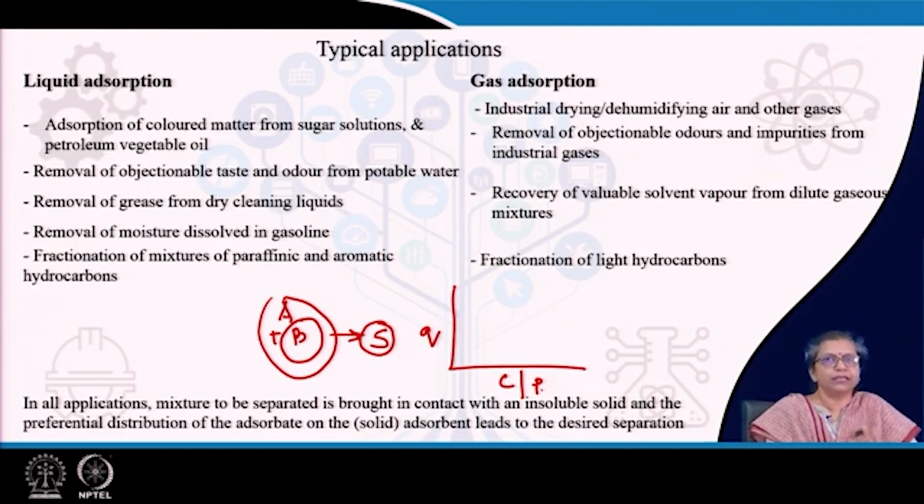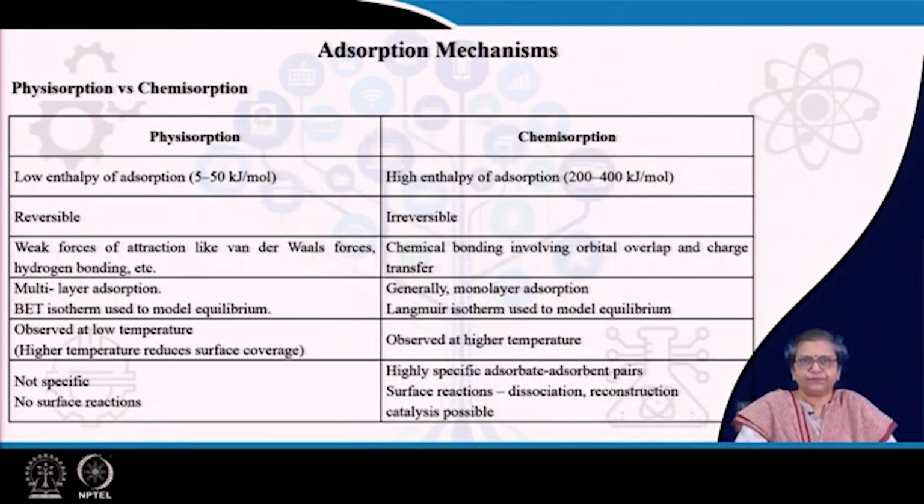And we have to remember that adsorption in this case also is governed by the equilibrium adsorption isotherm, which was discussed during our discussions on phase equilibrium. The best or the maximum possible adsorption that can occur is again governed by phase equilibrium considerations, or the equilibrium between the adsorbate concentration in the solid as well as in the fluid. So, therefore, this is also an interphase mass transfer, which is governed by equilibrium considerations.